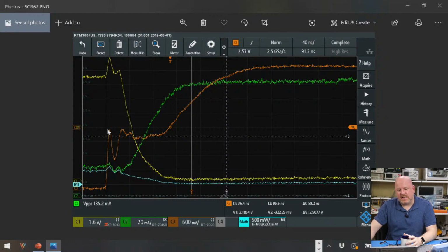What I didn't understand was why we saw this Miller effect. This is called a Miller Plateau. Why did we see that? And what I didn't realize is this is actually when the MOSFET starts to turn on. For some reason, I thought the turn on happened after the plateau, but I was wrong. Went back, reread my books, and realized what's going on.